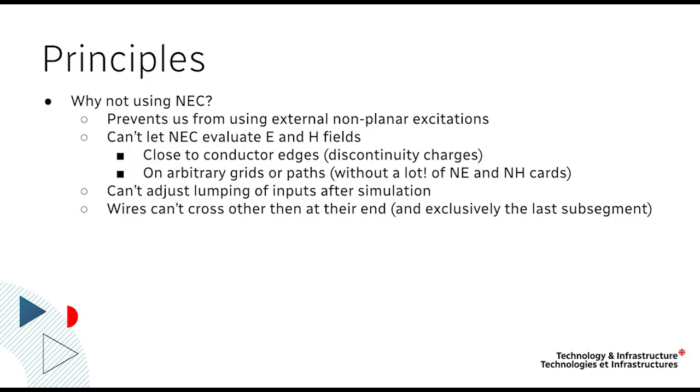Alright, so first and foremost, why not use NEC? NEC2 is available, you can use it on your computer, it's semi-user friendly. Well, it does not evaluate well E fields and H fields in the near proximity because there's some discontinuity in charges that appear at the end of the wire.